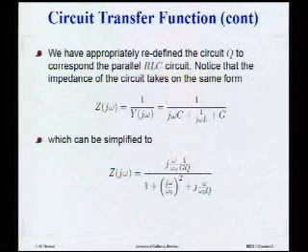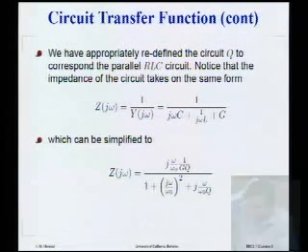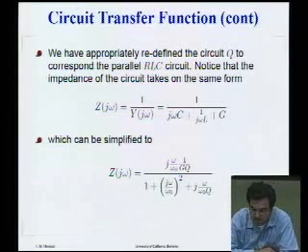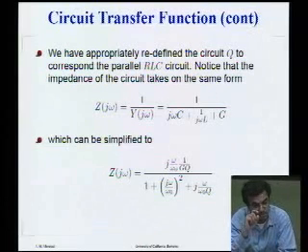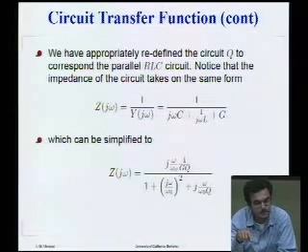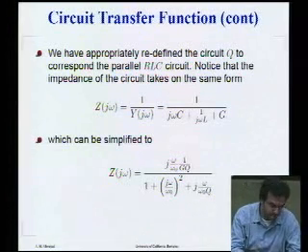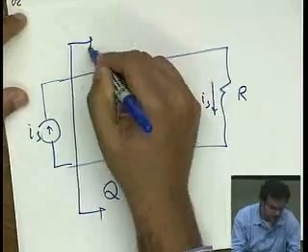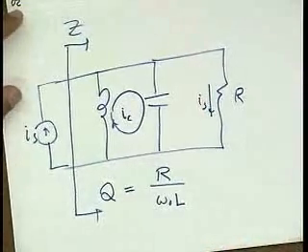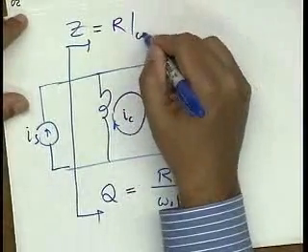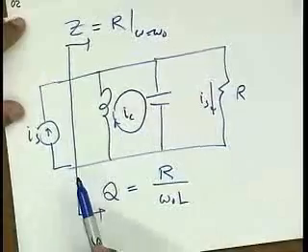Okay? And finally, often it's fruitful to think of the impedance of the circuit. Now, whereas the impedance of a series RLC circuit obtains a minimum value at resonance, a parallel RLC circuit obtains a maximum resistance at resonance, right? So coming back to the circuit, if I look at the Z of this circuit, I find that at resonance, it's equal to R, and away from resonance, it's smaller than that.